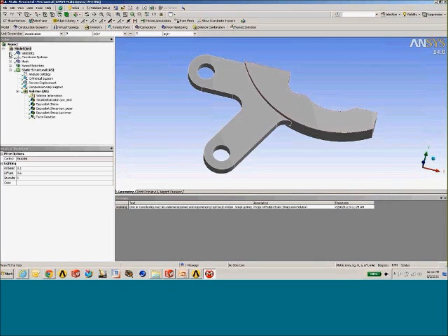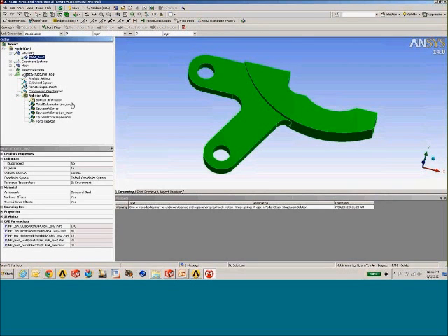We're going to find the parameters under the details of the geometry. So if I'm using Design Modeler, I'm going to look at the details of the attach feature that was used to bring the geometry across. In the case of mechanical, I go right to the geometry itself, and I'm going to find the CAD parameters listed under the details of that particular part. Now, I've already gone through and clicked on the box to the left of these, which adds each one of these parameters to the parameter set and effectively grays out the area where the value for that particular parameter is specified. That's now controlled by the parameter set on the project page.